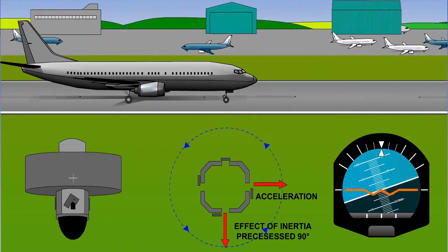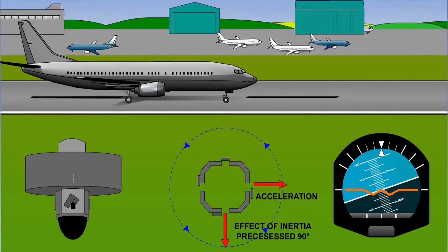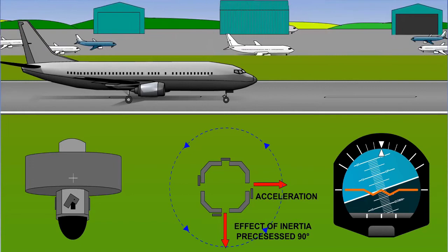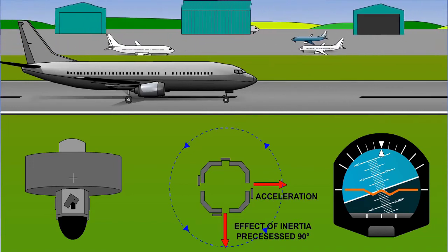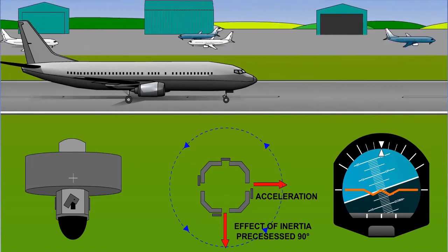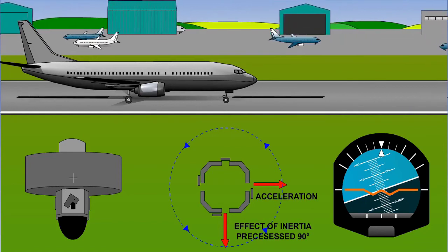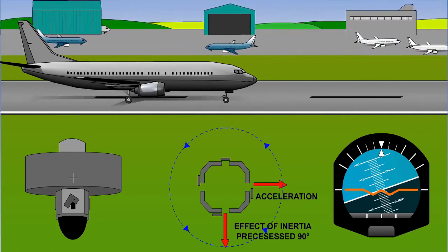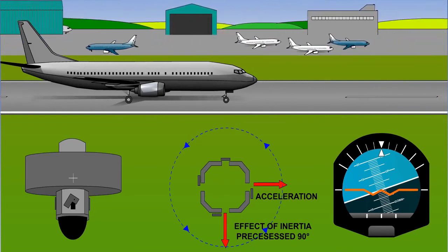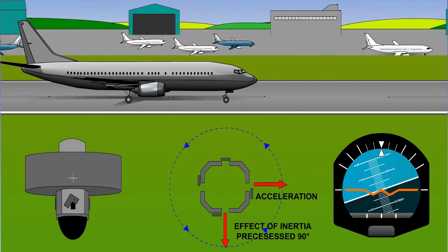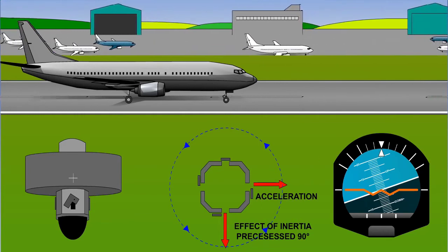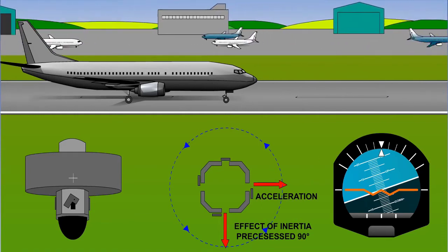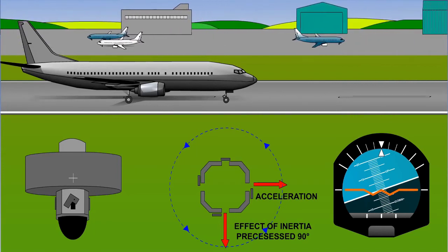To understand this, just remember that although the gyro assembly has tipped towards the port wing, the gull wing motif in this case has remained earth horizontal. If we think about it, and imagine we are flying on instruments in zero visibility, the false right-wing low indication can be visually interpreted from the instrument as a right turn indication, because of the movement of the horizon bar relative to the gull wing motif.